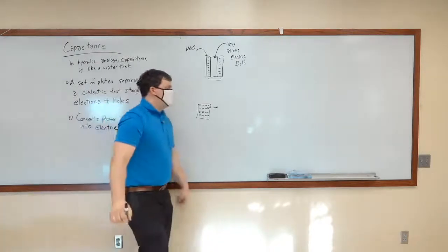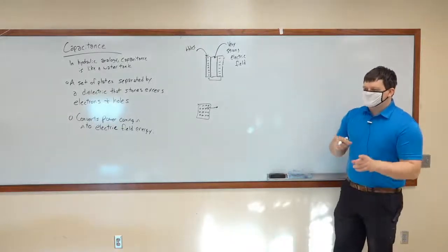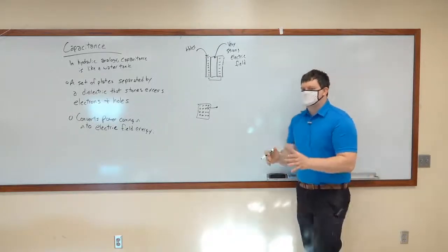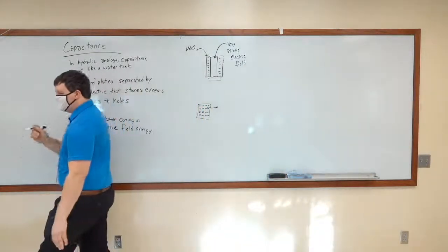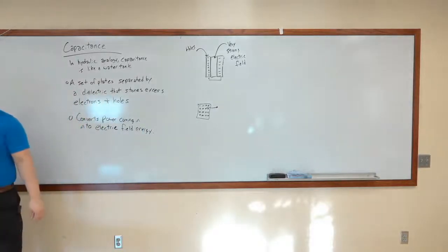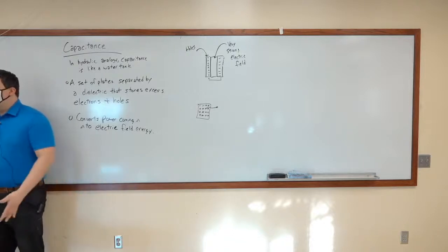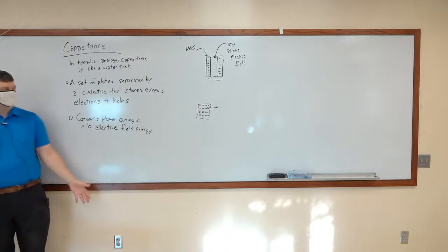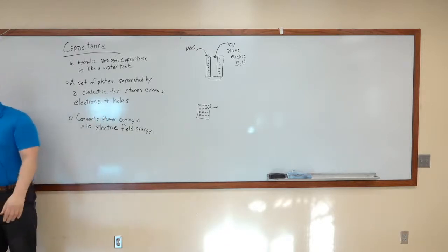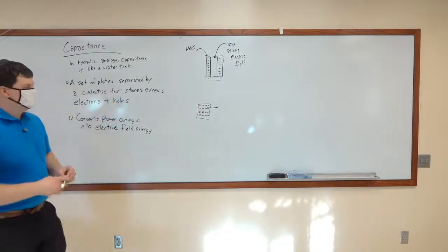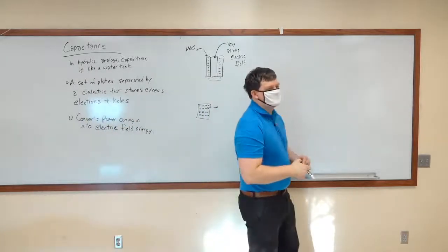So when we're calculating the power that is being consumed by a capacitor, we are calculating the amount of energy change that is occurring at the capacitor between the two plates due to a change in the electric field at that location. All right? That's how we're going to define capacitance, because ultimately when we're looking at other components, it turns out inductors also have a little bit of capacitance because there's a small electric field there. It's not huge, but it does exist. And when you talk about parasitic effects, we model it as having a capacitor for that reason.